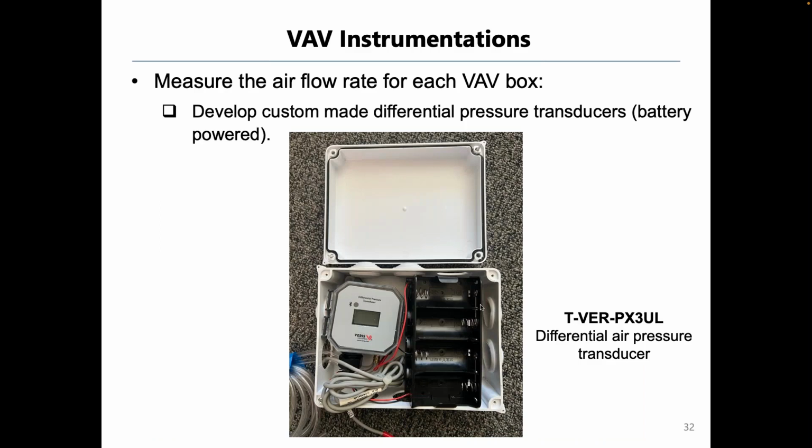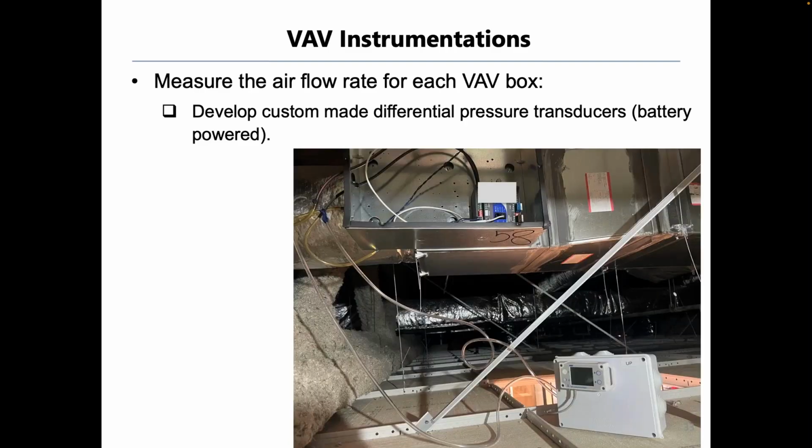The other thing we did: we had a lot of the old pressure transducers, but we also bought some new pressure transducers. One thing we haven't confirmed, but I believe these new pressure transducers were consuming less power, so the battery lasted longer. This is something others could confirm in the future, but it was our observation at first glance that these might be better for long-term installation.